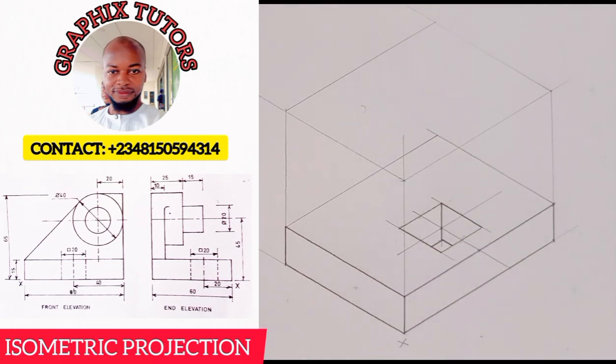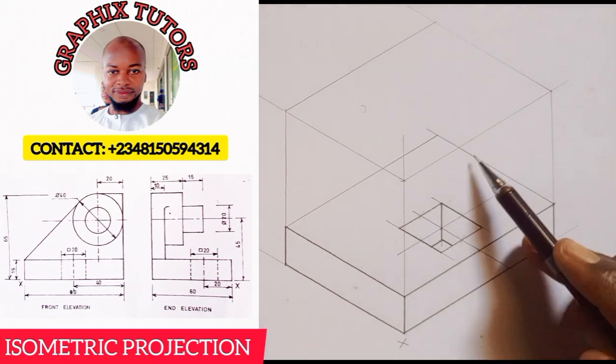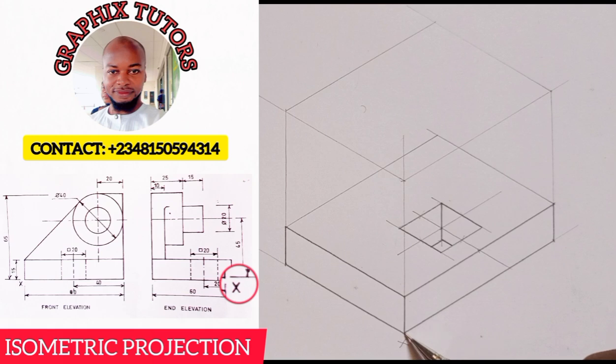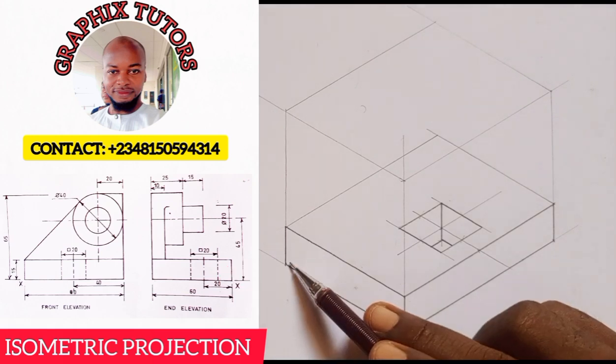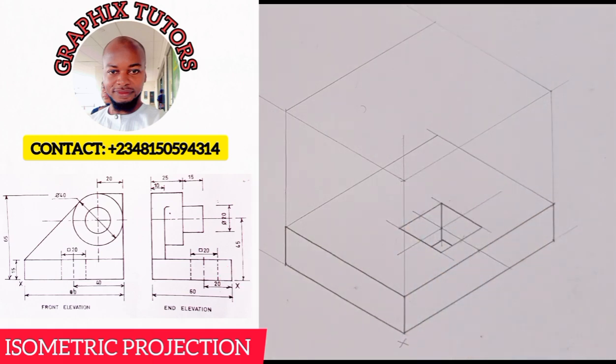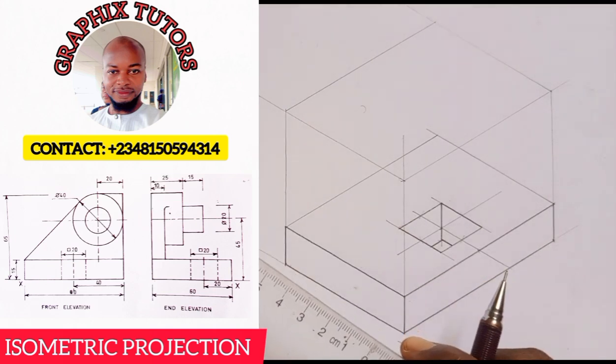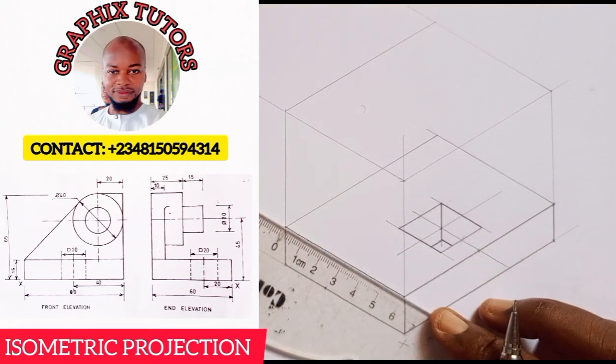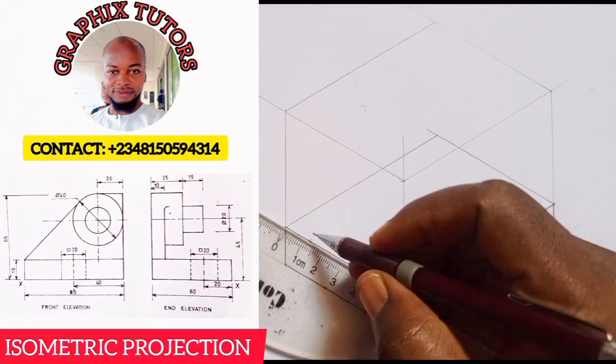Then the remaining one is that there is a circular figure. Are you with me? You've seen it as if it's at the front here, like this circular figure is here. But the elevation is telling me that since it's x and this is x also, then going backward means that it's at this side here. Are we there? So what I'll simply do, the thickness we have here is 10, as you can see from the top here. So I'm going to measure 10 here first of all from the end. We're coming from the end elevation. This end here is this end here. So I'm going to measure 10, from 0 to 10 here.